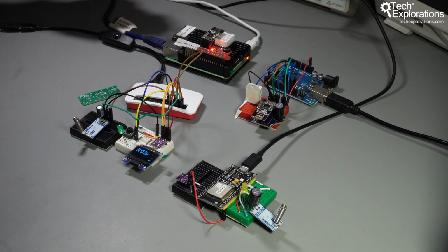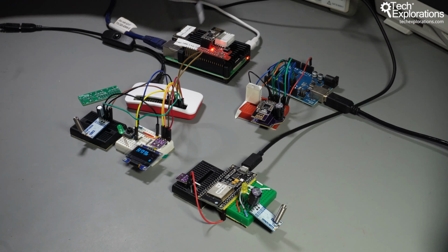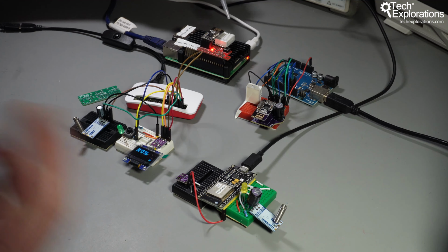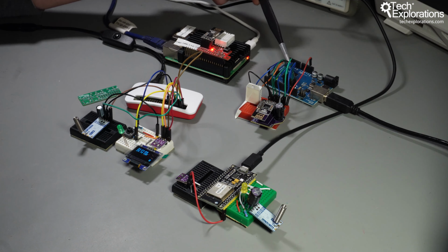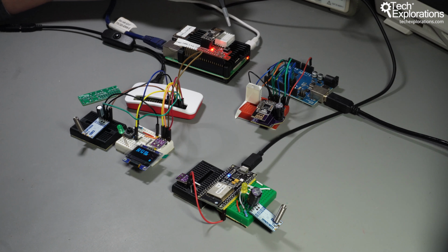Another issue that I wanted to improve on had to do both with the sensors and the communications. The DHT22 sensor is a little old. It's not really well implemented on the Raspberry Pi, on the Python that is, because of the way that its proprietary communications protocol works. It works well on the Arduino and microcontrollers, but not on microcomputers. So that caused things like delays and the application hanging and waiting for a long time, with nothing happening. It was one thing that I wanted to improve.